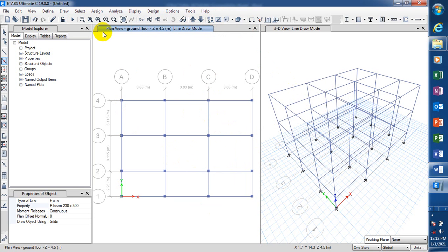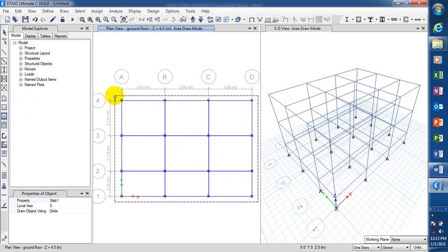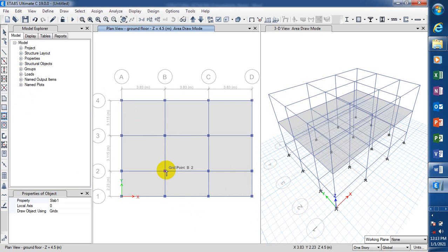our slab here. So to do that, all I'm going to do is to go down to my quick draw floor / wall, okay? You can see I can click on each of this, and then I will just insert the panel. Now I must come down here, my property, okay? This is slab which I have actually created. I have defined this section already, and then the property as well. So all I will do here is just to insert, or I can actually just highlight all of it, and you can see my slab has actually been inserted at this level.